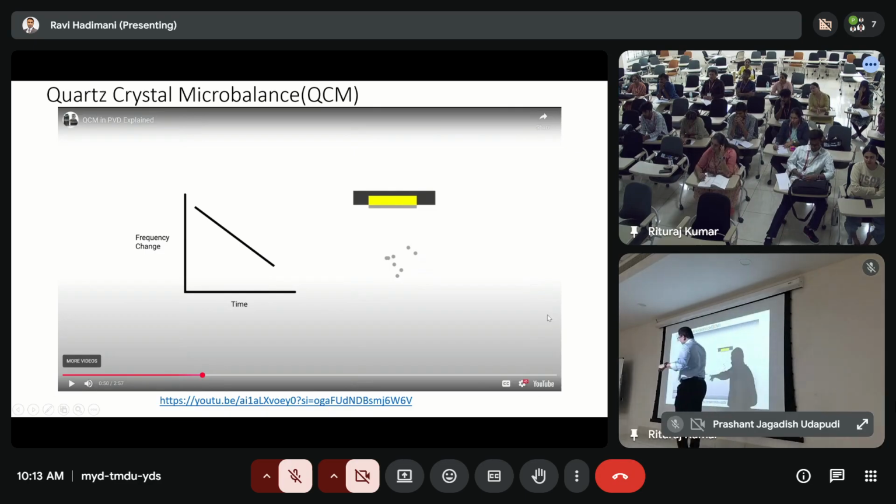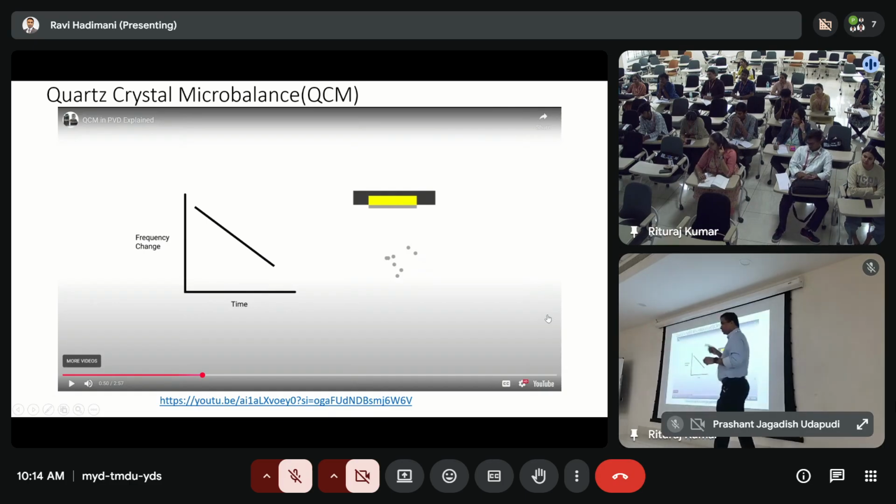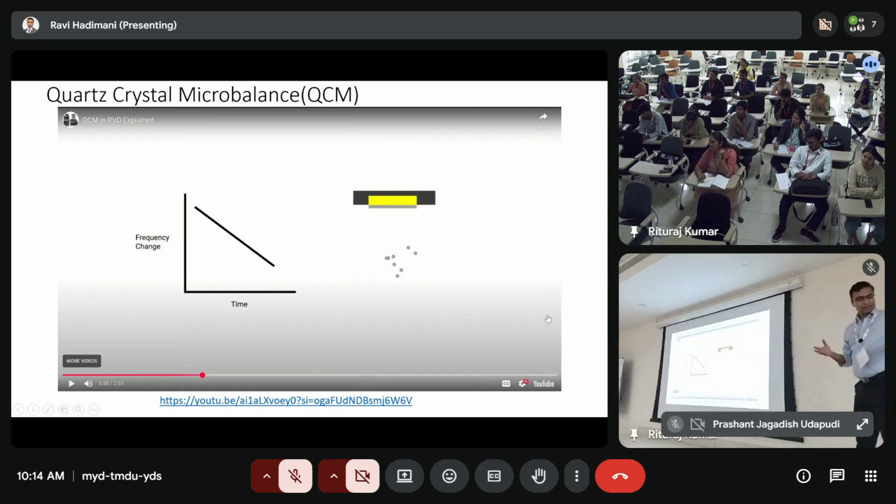That's monitored by this. So we literally keep looking at it, and if it is thermal evaporation, the curve is going really fast, and we target, say, only 100 nanometers. When it hits 80 nanometers, we press it, and then it goes to 90, 95. But if we press at 90, it overshoots. So it's really indispensable, a very convenient way. Otherwise, how do you determine the thickness of the film? How do you know it's 100 nanometers?